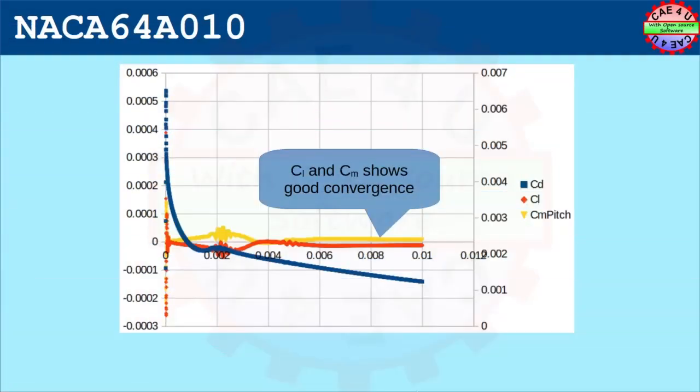Okay, that is interesting graphics. Let us look at the convergence plot. For 0 degree angle of attack, except CD, other aerodynamic coefficients have reasonably converged. So we expect a reasonable match with test data.